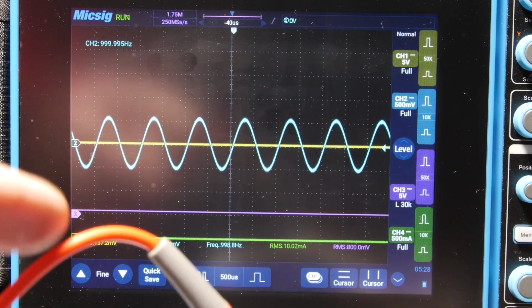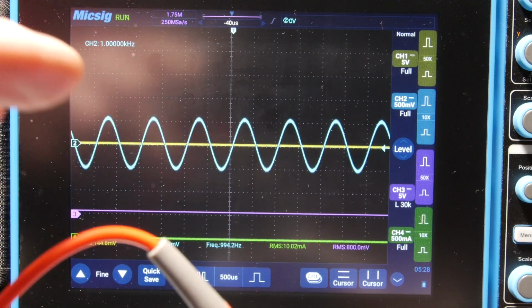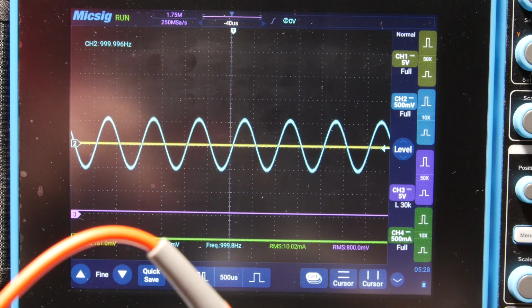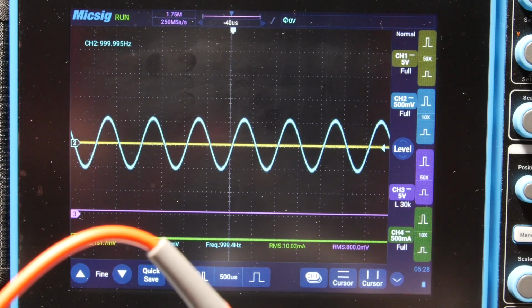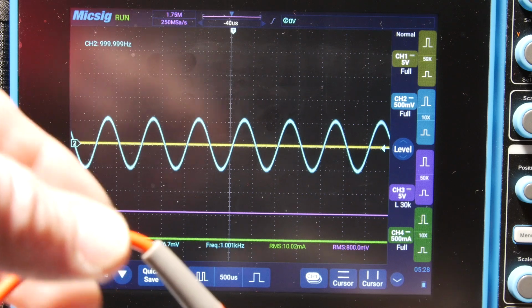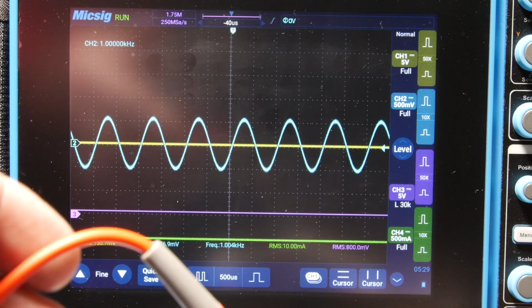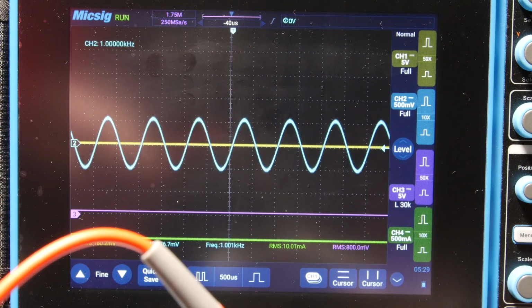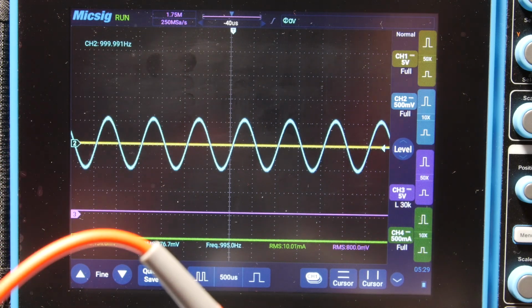Okay, sorry about this probe right here. That is just probing my voltage rail. So I'm going to just check the voltage as it comes up. So what I do is I use a variac, I bring it up a few volts, and then I make sure the voltage at my supply rail is the right polarity. I want to make sure I'm getting plus going to my plus supply and minus to my minus. So I'll move this in just a moment.